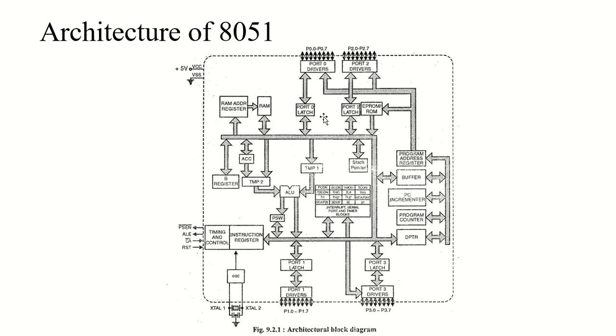The internal clock pulses are generated from a constant clock generator, so the count loaded in these registers has constant time. The register is incremented every machine cycle, and one machine cycle consists of 12 oscillation periods, so the counting rate will be 1/12 of the oscillation frequency.